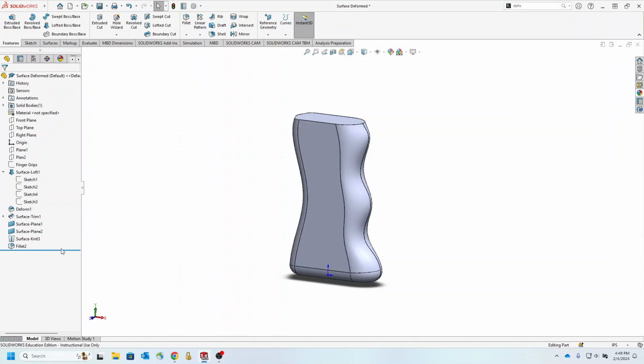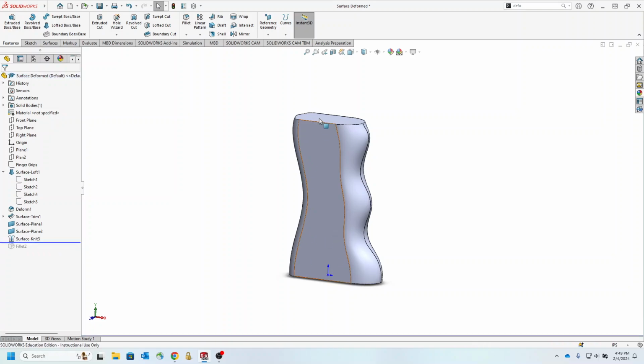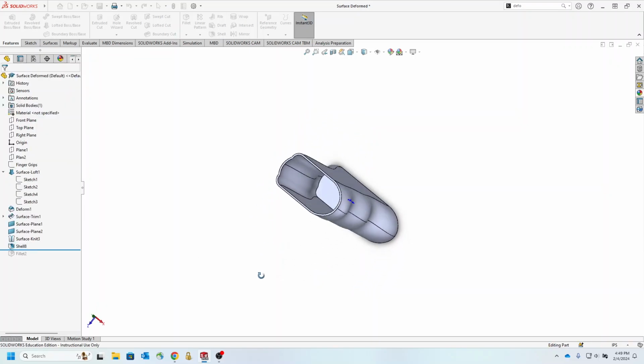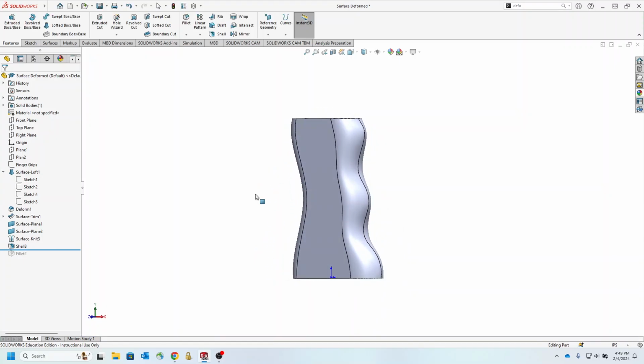first before the fillet. So let's roll back here. So give it this fillet, and then I'm going to select this edge and then shell with that face. Let's put it 0.5. That should easily shell that because the fillet does not exist. There you go. That's been shelled, and now we can roll back this one. Now the fillet would happen after the shell. That would be another technique using this rollback bar in order to fix that.